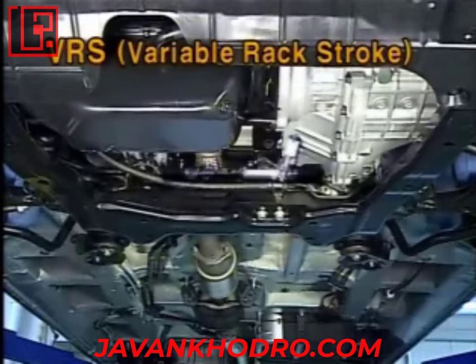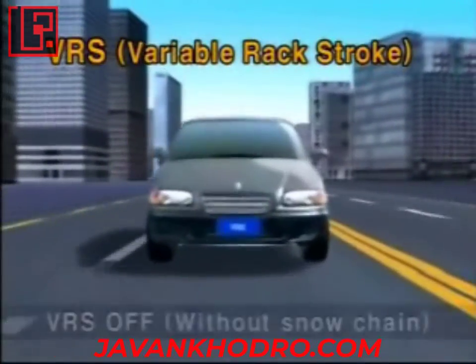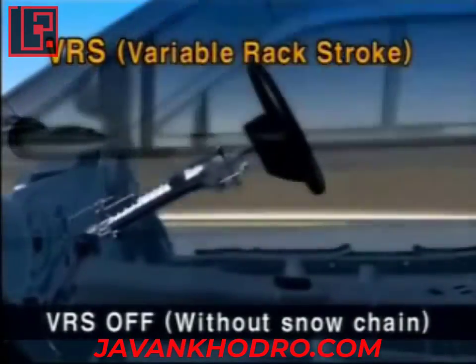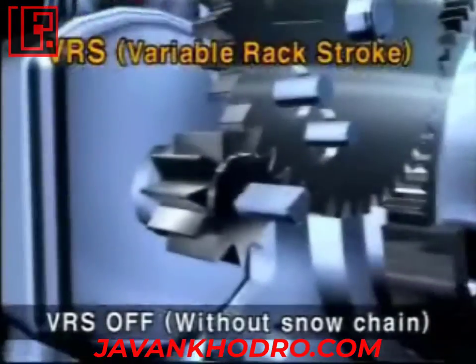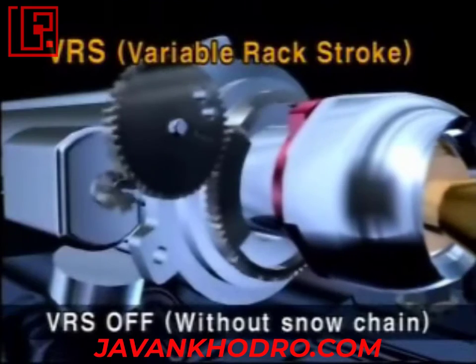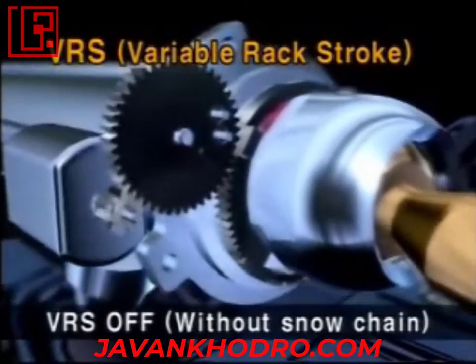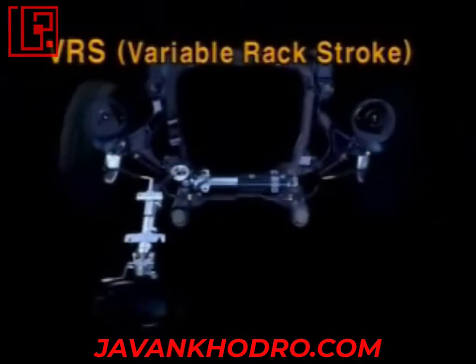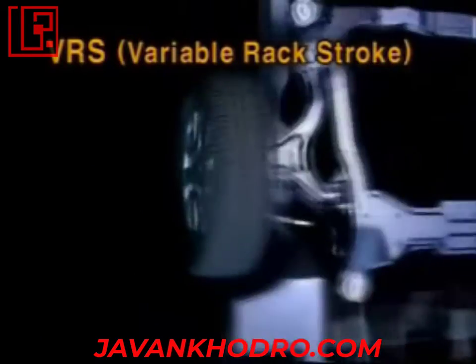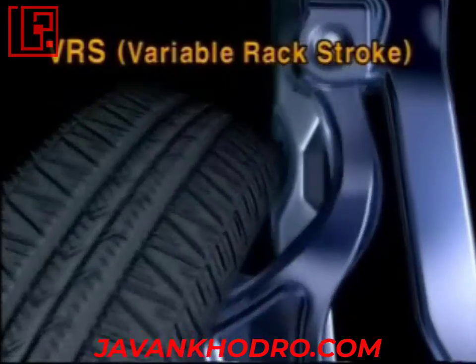The VRS system installed in the Carnival is an abbreviation of the variable rack stroke. When the vehicle is not equipped with a snow chain, the vehicle with the VRS system has an extra gap by 5 mm of a rack stopper, which limits the front wheel steering angle to change the rack stroke so that it is possible to steer more with this gap when parking or U-turning. Therefore, the Carnival can use the dead angle chain gap in which other vehicles cannot use.